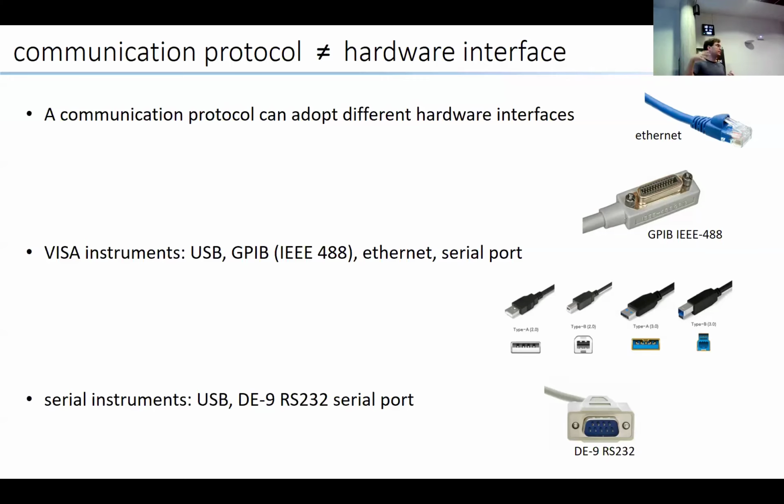For example, I have here a Keithley source measuring unit that we're going to use today. This one specifically is one instrument that can be connected through a GPIB port, this is IEEE 488. It can be connected with a USB connector, with Ethernet, and there are even more connectors. So you can decide how you want to program it. And they all use the same VISA communication protocol.